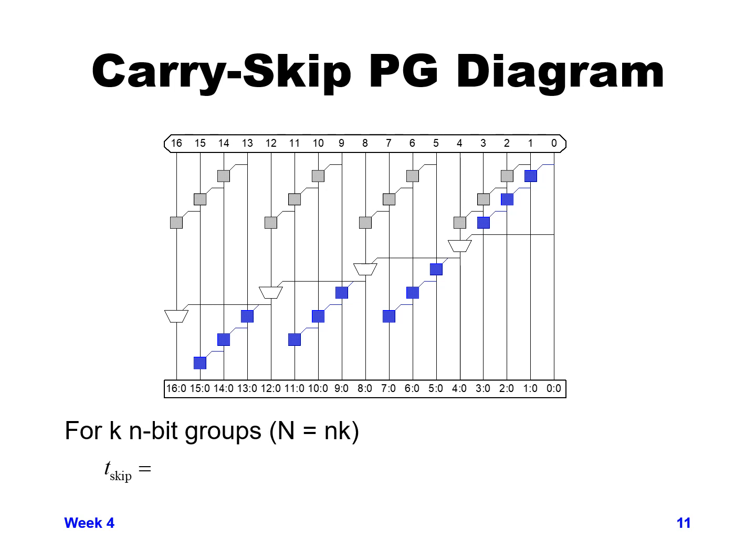So at the bottom there we have 3 carries that we need to go through. At the very top we had 3 that we needed to go through, and then we had the 3 white boxes in the middle where we were skipping each set of 4 bits.